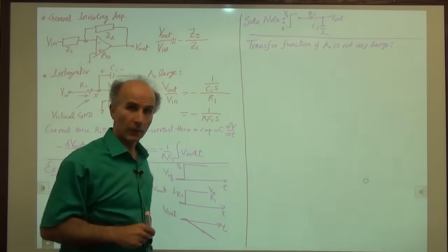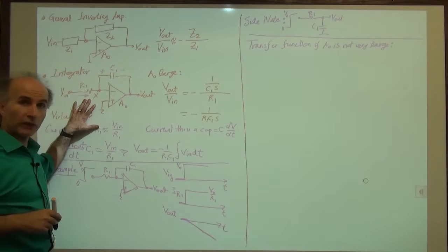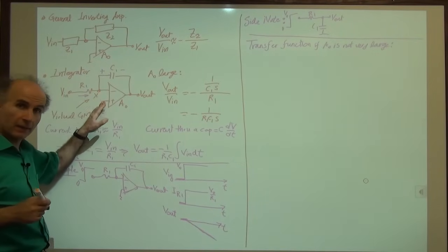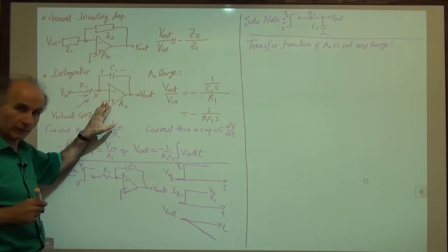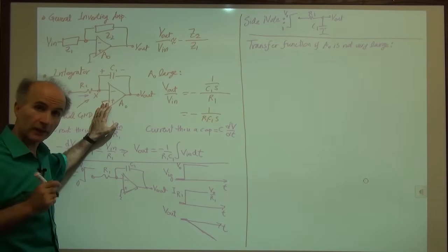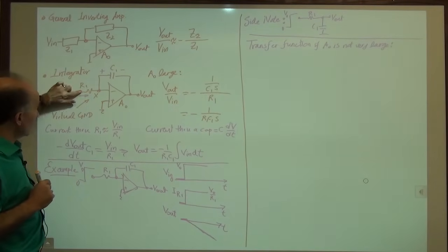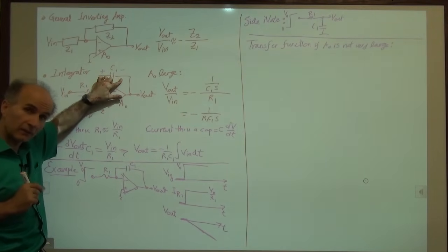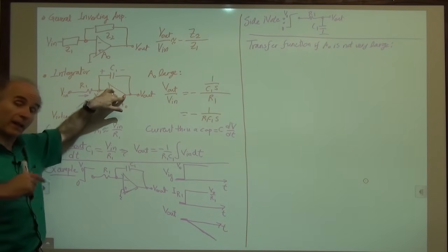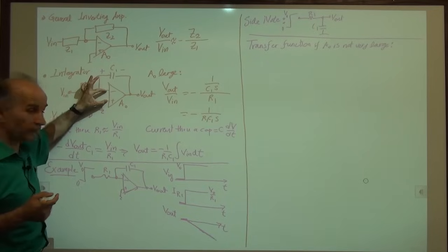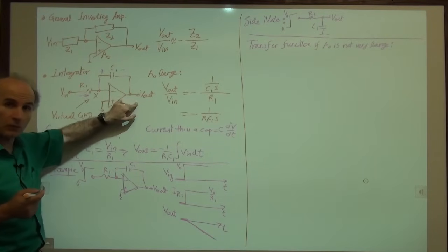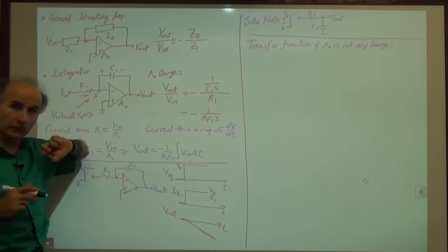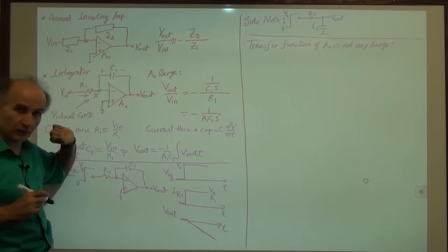Okay. All right, so we have to go back and write some equations more carefully, because we cannot say this voltage is very close to 0. It has a voltage, Vx, and then we have to write our equations accordingly. One thing that does hold is that the current going through R1 still has to flow through C1 in its entirety, because it has nowhere else to go. And another thing that holds is that this voltage difference times A0 is equal to minus V out. That's the general equation of an op-amp that always holds. So with these two principles, we can find the transfer function.